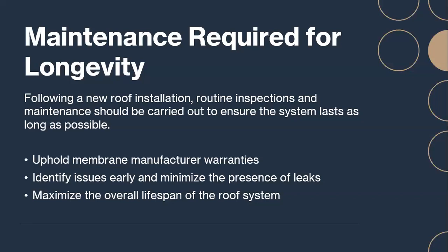Second, I'd say that maybe they could just, if they see anything near the mechanical room or near the entrance point of the roof, if they see large areas of debris or vegetation, that's a good sign they should call a roofer. If they see any of the concerns that Kelly brought up about installation of penetrations or anything like that, missing vent caps, if they see birds or droppings from birds on the roof, and if they see any sort of exposed membrane within an inverted roof system.